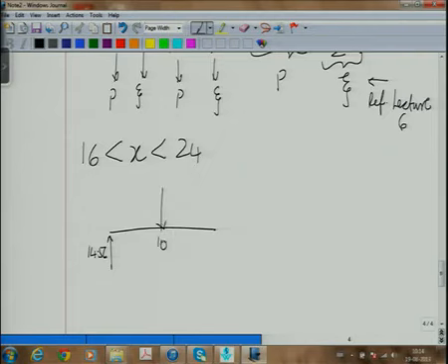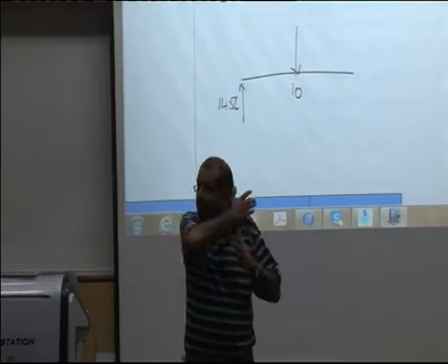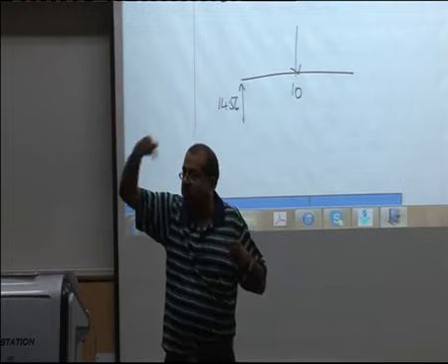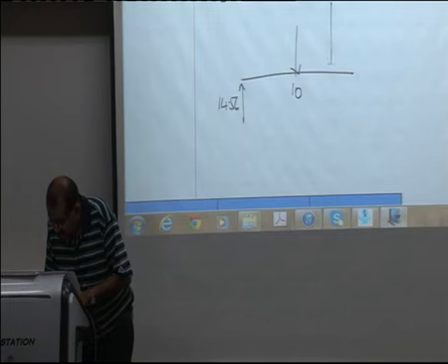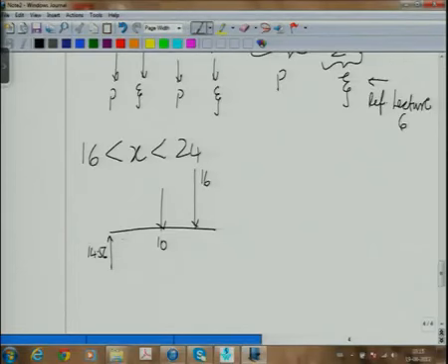Now what do we do of the distributed load when I go from 16 to 24? I am not cutting at a section which is in between the load. The load has already been crossed. So what I can do is replace it by its equivalent. So I will put it as a force equal to 16, and this distance is 12.